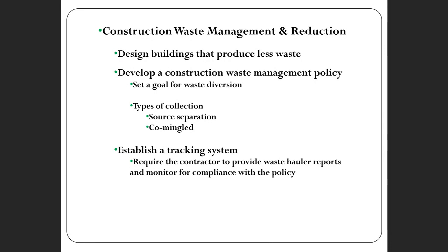We talked a couple of times last week about ways of reducing construction waste. Obviously, the first thing is to design buildings that produce less waste. In the first lecture, we talked about designing around a standard module that ties to standard dimensions of materials, so we reduce cutoff waste. Design things on a 2-foot or 4-foot module, rather than 5 or 7 feet or something not related to the dimensions of your materials.